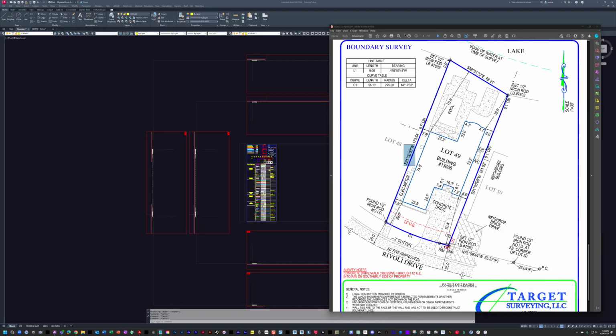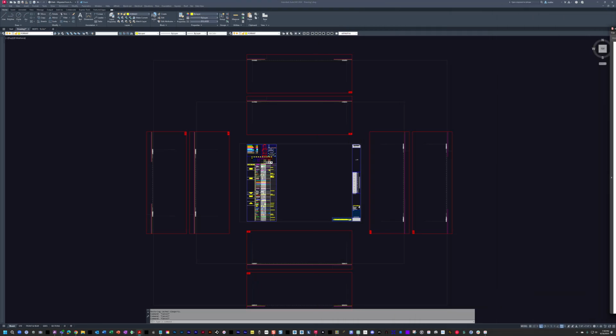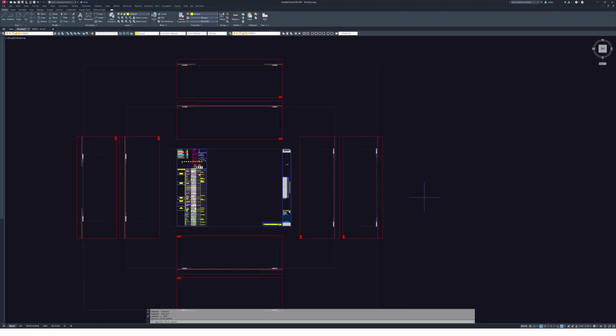So to follow, I'm going to pull this off screen, but you can see the information here. And we're just going to start drawing a line. It doesn't really matter. I hit L for line and start drawing. I'm going to come down here, and in my bar I'm going to type in at 173.64 feet. Actually there is no space, sorry about that.